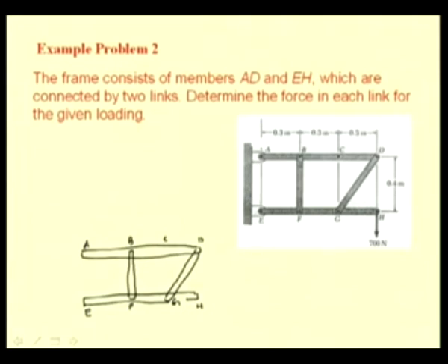If this structure has to move, since we have this 2 force member BF connected at this point F, this part of the frame EFGH can move such that the point F traces a circular path, because this body BF is rigid, so its dimension cannot change. So, any movement that is possible is such that the point F moves along a circular path.